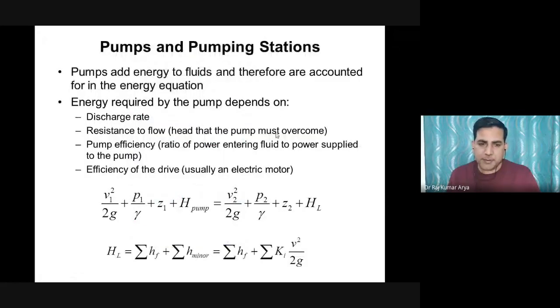So what we have is the pump and pumping system. You actually provide the energy balance in the pump. Before entering the pump, the fluid has some energy. And once you add a pump, you are imparting some energy. So this is the energy delivered by the pump, this particular component, H pump. It is the energy delivered by the pump per unit weight of the fluid. So the dimension of this is meters actually.